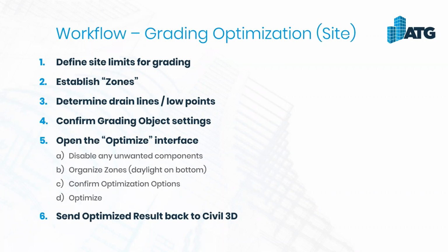The tool is going to go through, and we'll watch all of those iterations, some of the different animations, so we can keep track of whether or not this is going well. And then we're going to take that and send it back to Civil 3D. Now, this is not going to be all of the break lines and perfectly manipulatable stuff. This is going to be a LandXML import into your Civil 3D design.